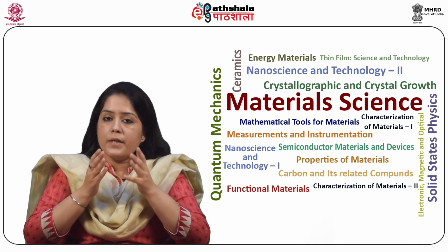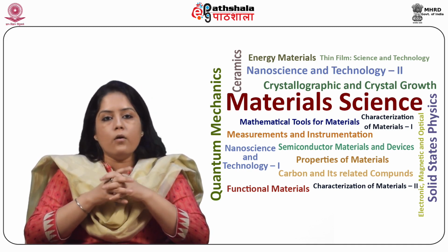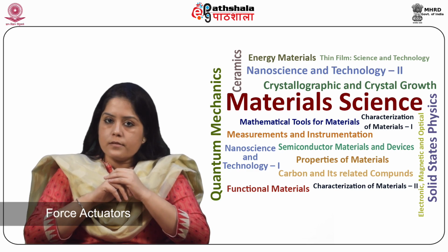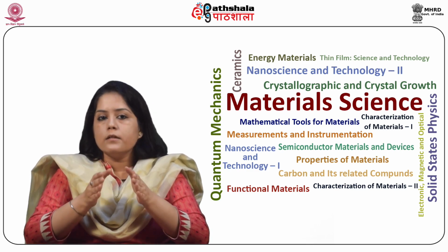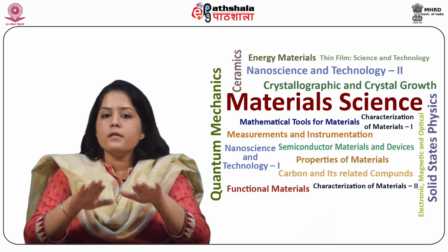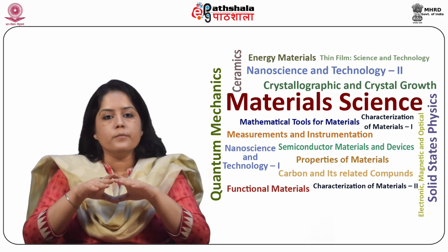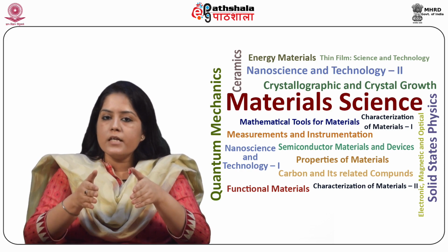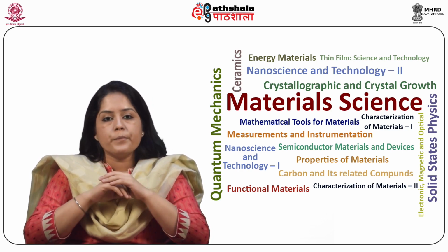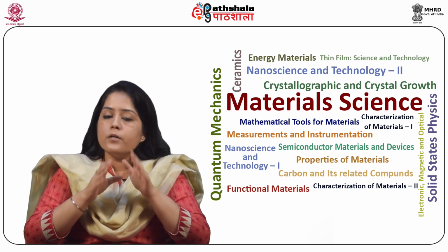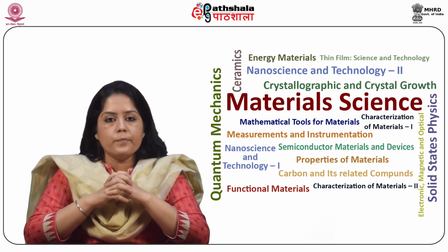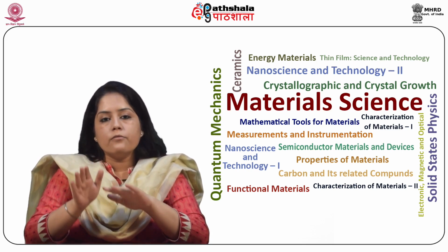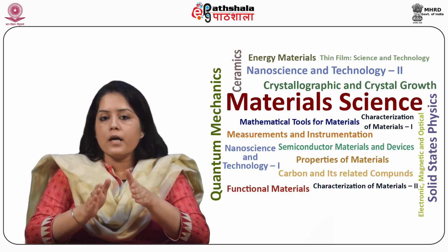So the basic applications of these alloys are: first, force actuators, that is, they exert force over a considerable range of motion. Second, in joining, that is, in cylindrical sleeves joining tubes. Third, they are used in proportional control, that is, the valve controls the rate of fluid flow by careful heating.